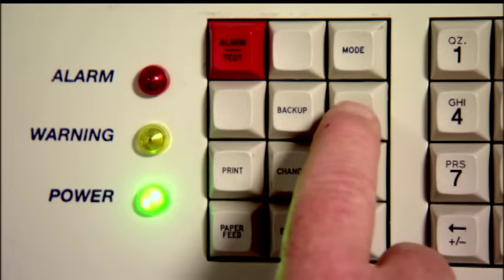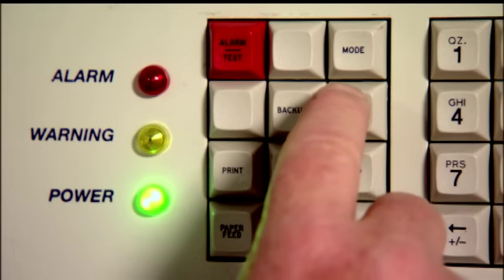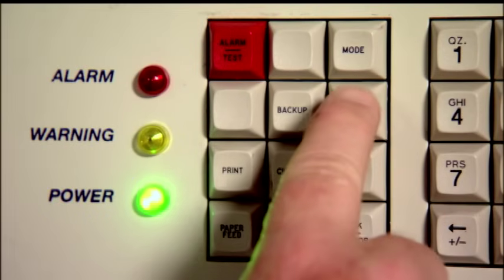If it should become necessary to start a manual test, you will first need to take the product to be tested out of service. Activation of the product during the test will abort the test and require starting the process over. First, ensure access to the product has been closed. To start a pressurized line leak test, press function to display the message Start Line Pressure Test.